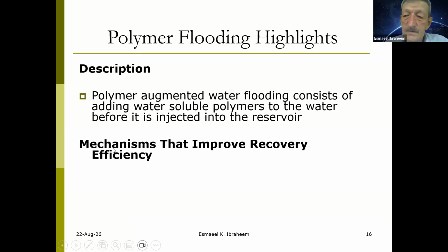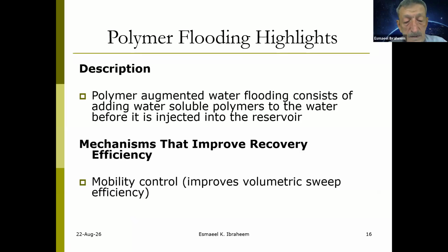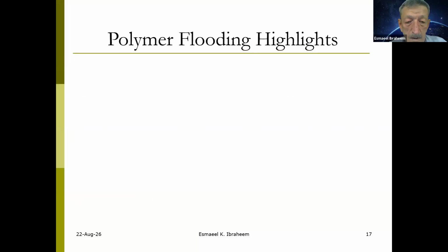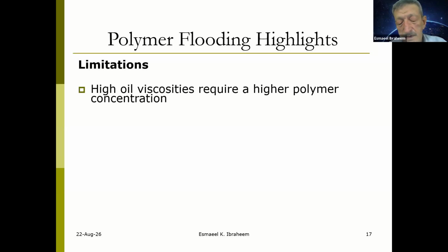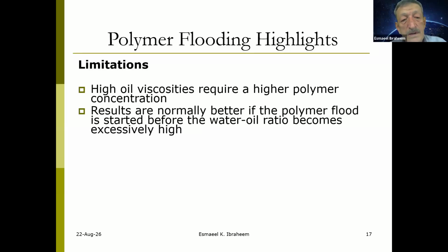Then, what is the mechanism that improves recovery efficiency? This is mobility control that improves volumetric sweep efficiency. That's the main mechanism of the polymers to improve oil recovery. But as I said, polymer or any process has its own limitations.